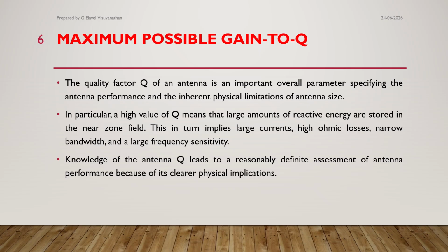In particular, a high value of Q means a large amount of reactive energy is stored in the near zone field. This in turn implies large current, high ohmic losses, narrow bandwidth, or frequency sensitivity.